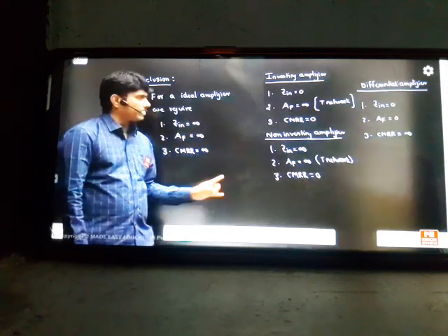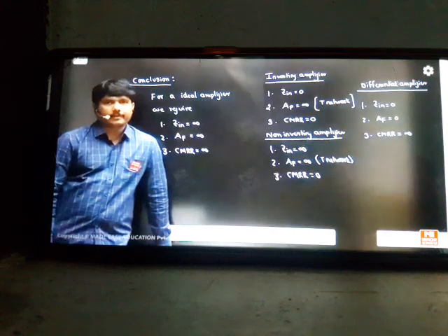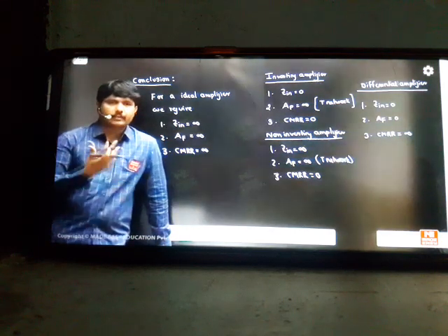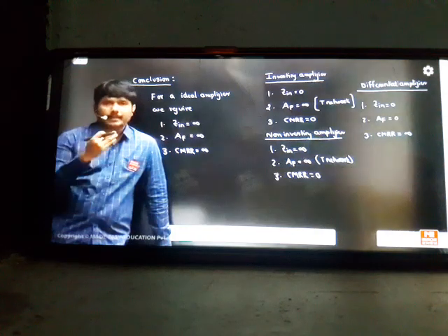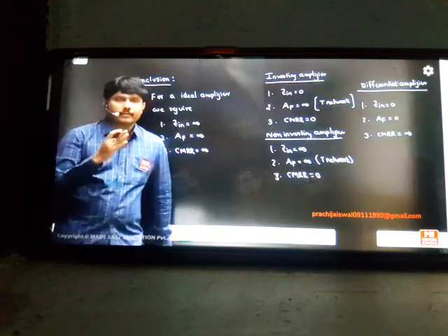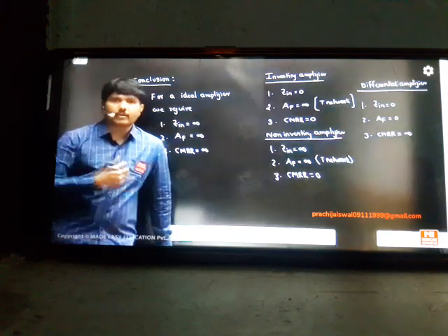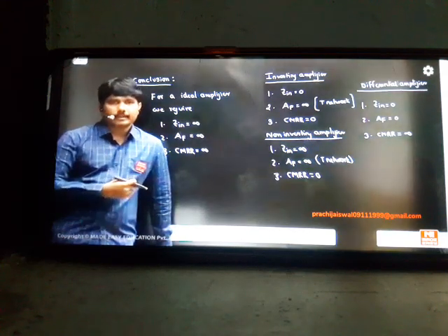You can see any amplifier is not satisfying these 3 conditions at a time. So who will satisfy all these conditions? Then only it can work like an audio amplifier in electronics, which is called our basic amplifier in our classroom. So that's why it got the name instrumentation amplifier. You have to design an amplifier in such a manner that it gives all 3 properties in the system. High input impedance it has to provide, gain also should be high, CMRR also should be high. But he said one important point, size is not a matter here because you're talking instrumentation. So how many op amps you like you can take, how many amplifiers you like you can take, but all 3 properties at a time you have to show. That is what is called the instrumentation technique.